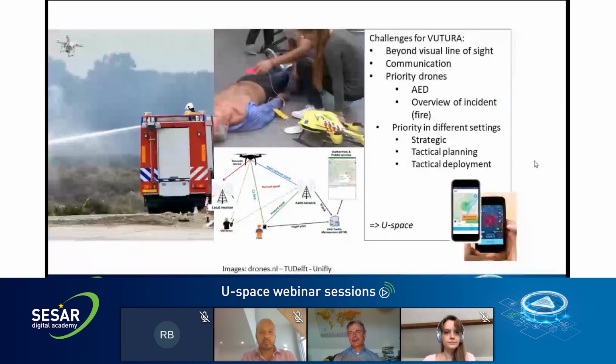First of all, we tested the strategic conflict detection between drones. So the priority drone was planning its flight, providing the information to the U-Space, and through the U-Space, the other drone pilots were informed and cleared the way for the emergency drone.